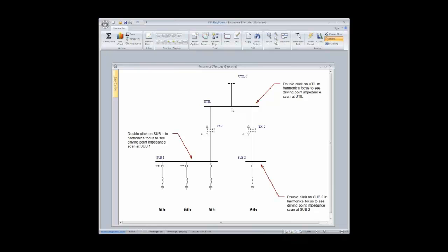Now, in most cases, the utility bus voltage has fairly low distortion. I mean, probably 1–2% is very typical. But you would be surprised that if you created or presented a low impedance path to the utility system for, like, a fifth harmonic filter, for instance, you may get very surprised at how much current you absorb.